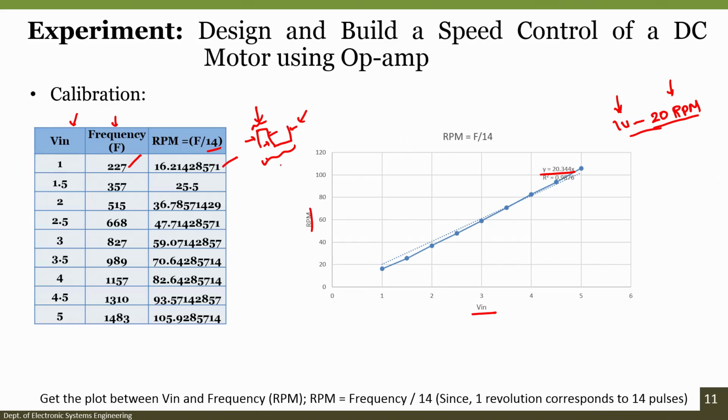So, for that purpose, we made one particular term fixed. Either we can keep the frequency at which this is operating fixed, and by changing the pulse width, which is nothing but a PWM signal, we can integrate that signal and observe the varying output voltage with respect to the change in pulse width. But since that would be difficult, we have interfaced the output of the encoder to a monostable multivibrator.